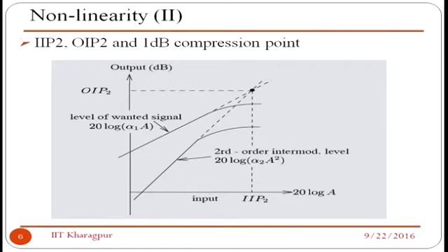This is another point. I have not gone, in amplifier design, through the third order intercept points. What is the third order intercept point? It is twice omega 2 minus omega 1. But here I am giving you second order intermodulation products at omega 2 minus omega 1, which will be more important in today's technology node, where you want to reduce the hardware count in your chip, and you like to have a simple low IF or zero IF kind of transceiver system.